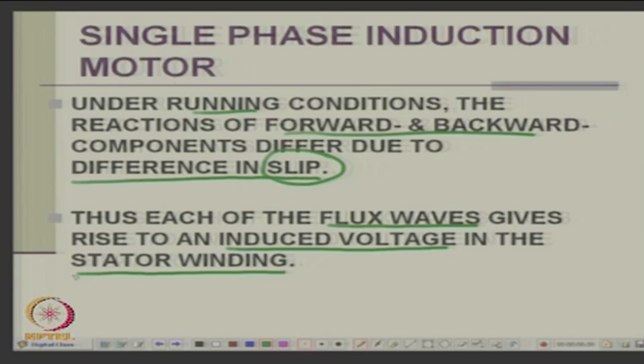Any doubt at this? We are saying that each current passing in one winding will give rise to forward fields and backward fields, which induce voltage in its own winding, and it also induces voltages in the other windings located in the stator. It may be 3 windings, 4, 5, 10, or n windings. They will all have voltage induced in them. Now, you define an impedance from the voltage induced: you can have a self impedance or a mutual impedance, as the ratio of the voltage induced to the respective currents.